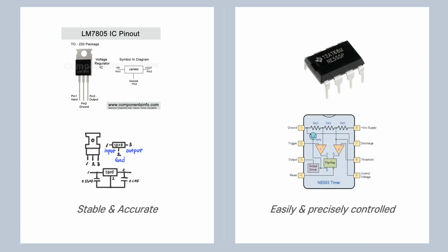By the way, we decided to supply power of 12 volts, but the operating voltage of the NE555 element was close to 5 volts. Therefore, using the circuit of the 7805 element, a 5 volt VCC was created.